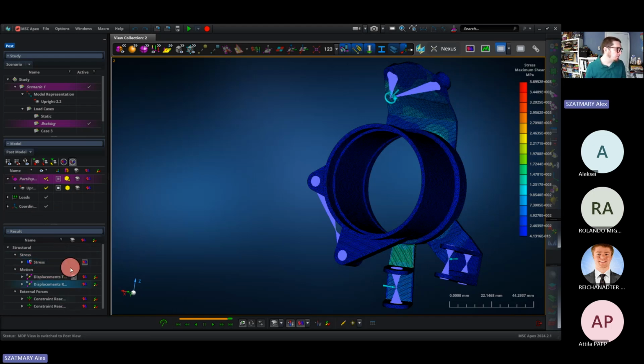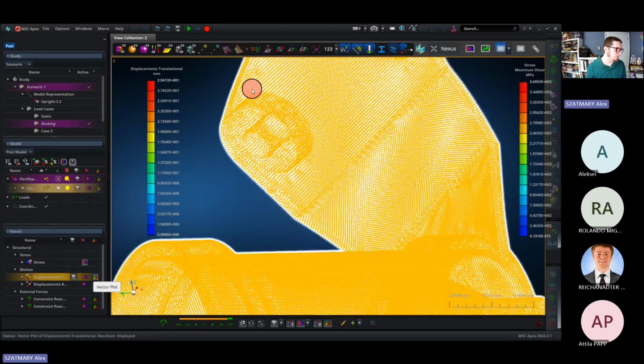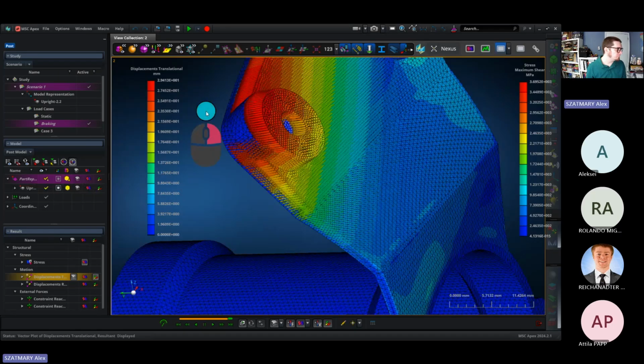And we can change which quantities we're looking at by clicking down here. Like I could make a vector plot of displacement results very easily just by clicking this vector. So we see a lot of vectors, one for each node, showing how each node is displaced. Coming to the bottom, we can get some more control over how our model looks. So for the deformed shape, we can change the scaling.